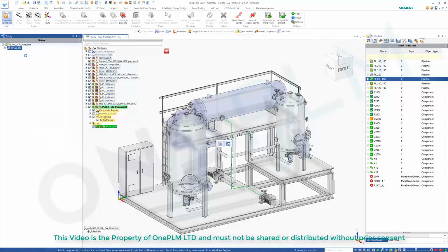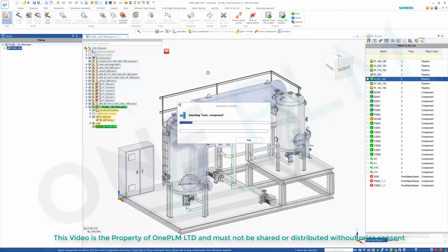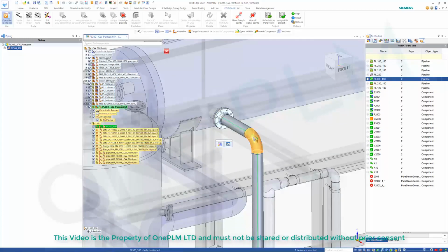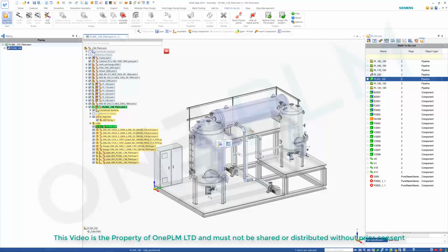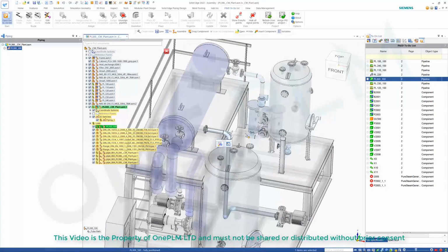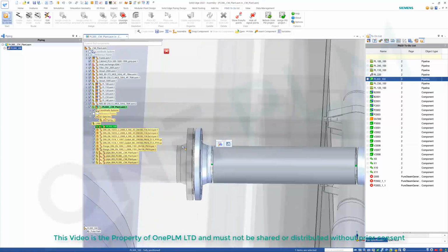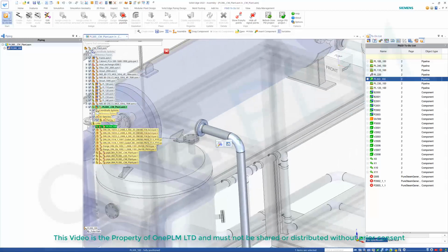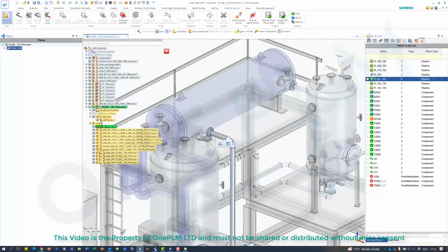And let's just click recalculate, and that's then going to read the data from what we've got. So all these parts have got an input and output location. You can see we've got our flange, our elbows, medium on there, and then we've also got our gaskets on there. We've got our gaps, which are also set in the specification as well.